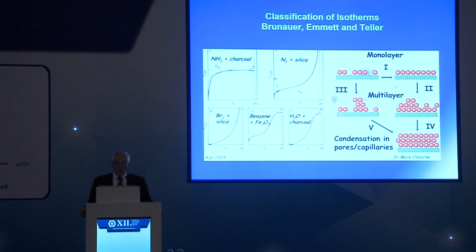You'll see that for a long time in the distant past, many rotor manufacturers actually used lithium chloride wheels as an adsorbent. The problem with lithium chloride is that in very humid conditions the material can deliquesce; it actually forms a liquid and can migrate in the wheel. That's where you'll see the vertical line on the one that says 2 in the corner, which goes beyond very, very high uptake and actually forms a liquid system and migrates on the wheel. So lithium chloride has been abandoned in commercial applications. In some industrial applications it's only used as a replacement for manufacturers or producers that like its performance. But these are the different isotherm shapes.